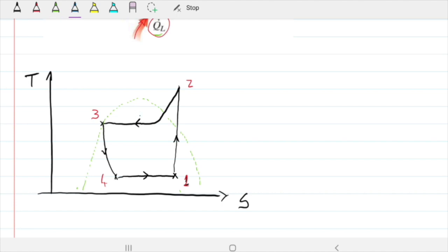Okay, we have QH over here, and that QH is completely related to, in our case here, the water that's coming through and grabbing this energy and taking it away. And down here we have QL, which is related to the energy we need to remove to keep the place at -30. So at this point, it might be easier for you to understand why we have the limitations, right?